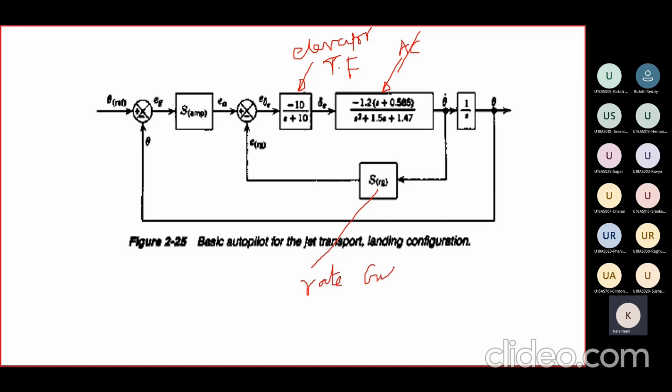Rate gyro sensitivity. Then it is theta dot of s. If you put an integral, then we will get theta. Then it will be compared to your reference pitch angle. Whether you have an aircraft, you decide whether to use a reference pitch angle or not. Suppose the aircraft flies at a certain altitude with a desired pitch angle.